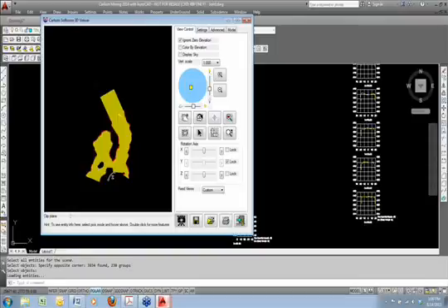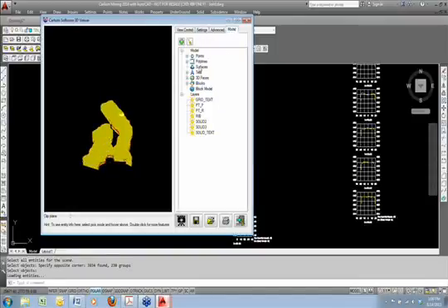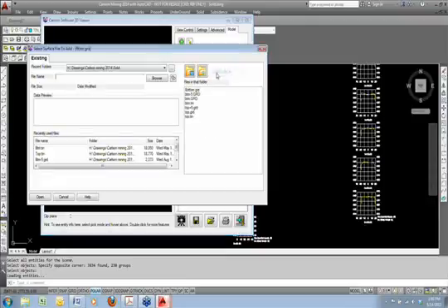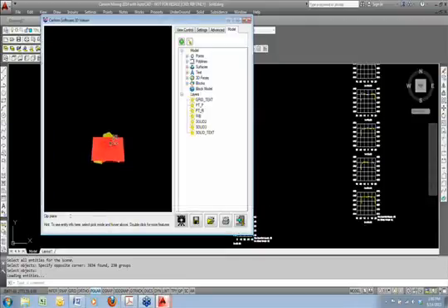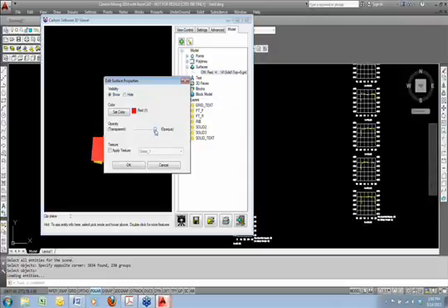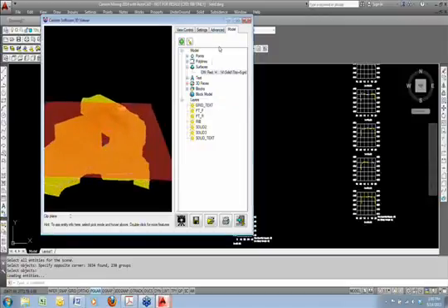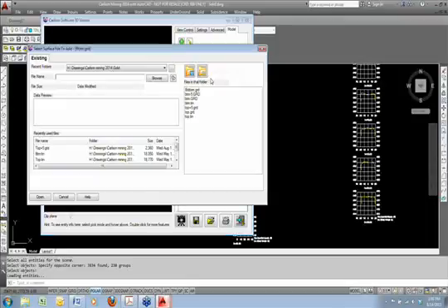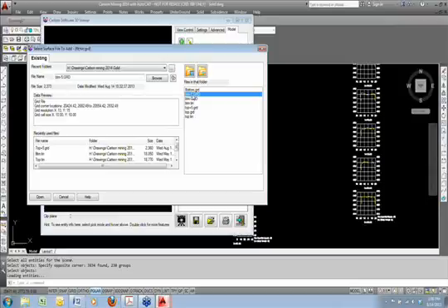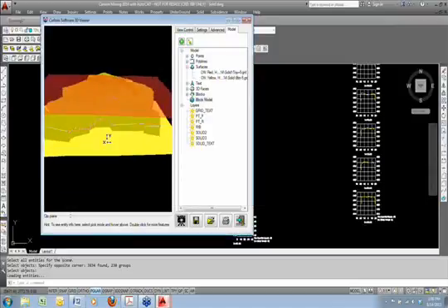And then the reason I just reported out only one strata was because if I bring in my surfaces, add a surface, I had in my pre-calculated model, I had top +5. Let's make that transparent so we can see the solid behind it. And then I'll add the next surface, which is just a bottom. Bottom I did -5. So that was what defined the rock zone.